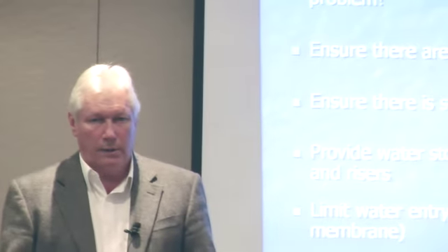What you need to be doing is designing it out. So once again, this is an issue for you. It doesn't just happen with stone, it can happen with almost any kind of surface that's got water underneath it, ceramic tiles or the like. But what you need to do is make sure that the water that gets down into the substrate drains at the neck of the drain. It can get out of the system.